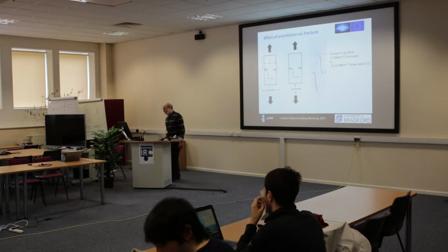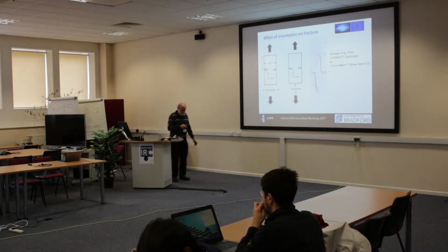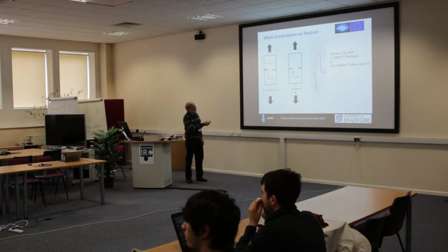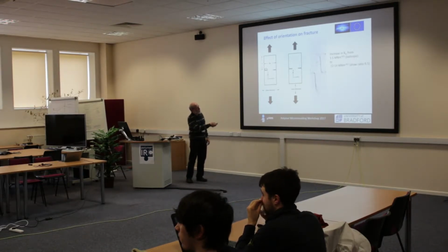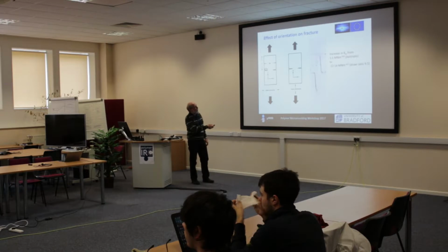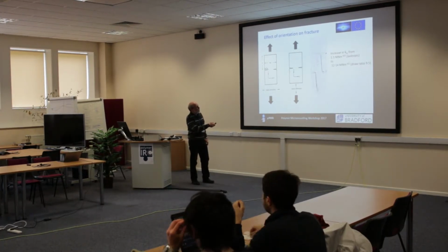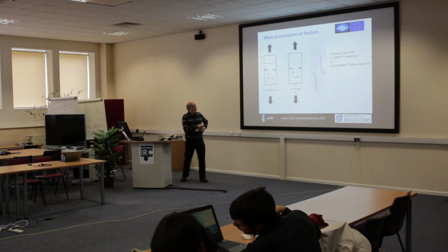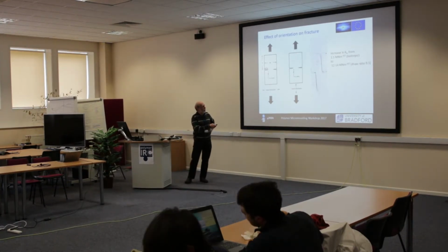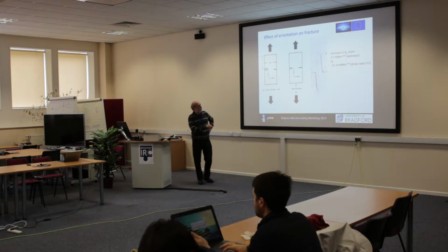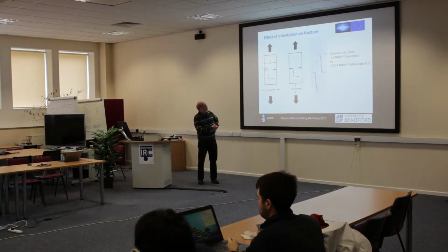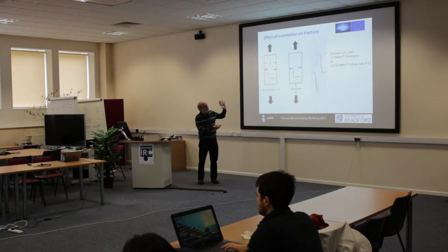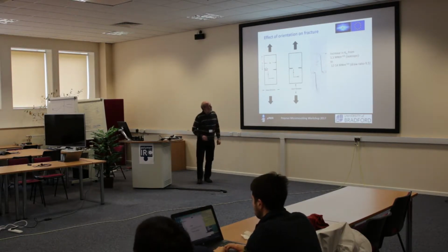And you find the fracture toughness does go up, and the behavior of the fracture in an oriented body, if it's a test like this, where we've got the draw direction vertical, then the cracks don't go this way normally, they'll go this way, at some angle. So it's somewhere between the easiest direction, which is along the axis, and the direction of the biggest stress, which is going to pull it apart. So it's some oblique angle.